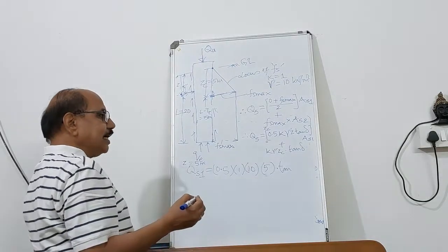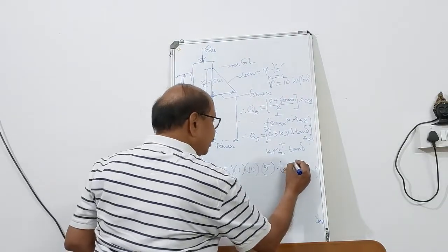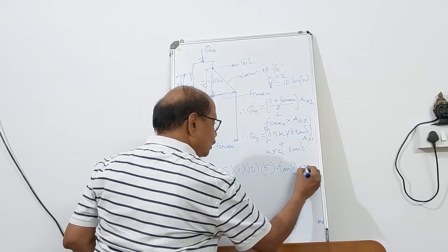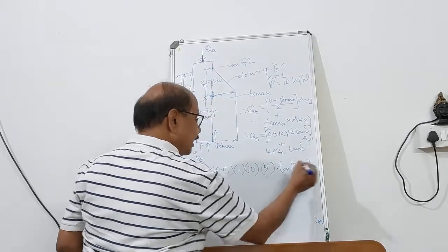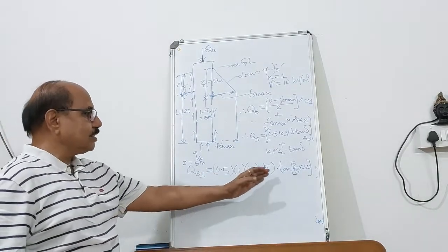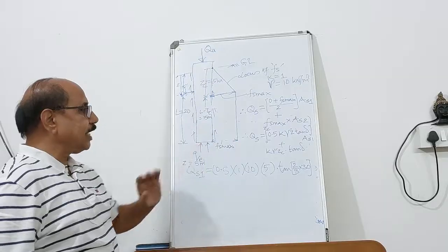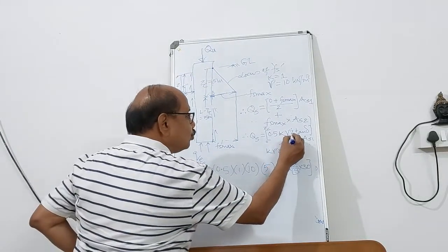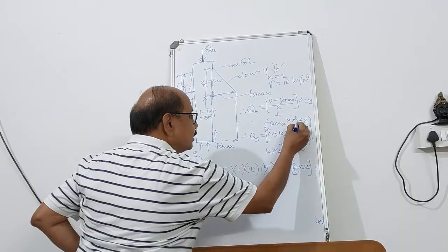Tan delta is going to be 2/3 of 5 because it is loose. So 2/3 of 30 degree. That means delta becomes 20 degree. So your first term is going to be like this, for Z up to 5 meter.